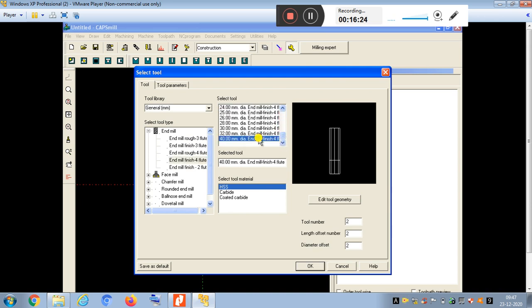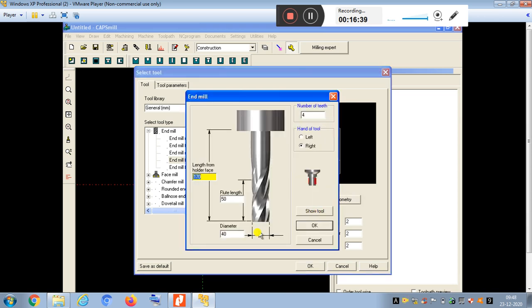Select the maximum tool diameter here, because this component is huge, so if you select a smaller one, it requires maximum time. So 40 is there. In industries, if you have a larger one, you can select that. Otherwise, you can edit it here. If it is not there, just for analysis or simulation purposes, you can select this to see how it is going to work.